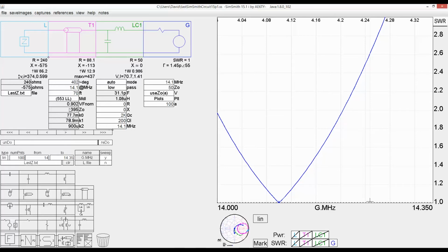And with the losses due to the dielectric in the material, the mismatch in impedance just exaggerates that. So if this happened to be a way better match to 395 ohms, this value would be a lot smaller. And you'll see that on some of the graphs for the other bands, where by coincidence it just happens to be a better match.